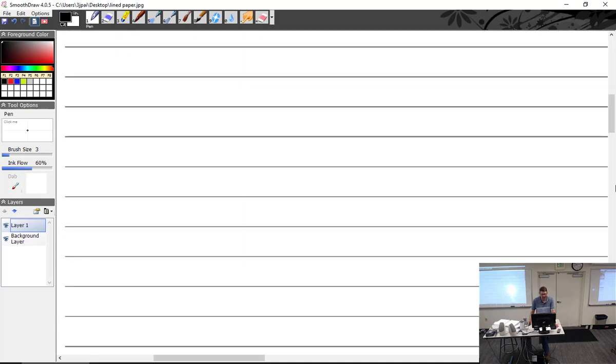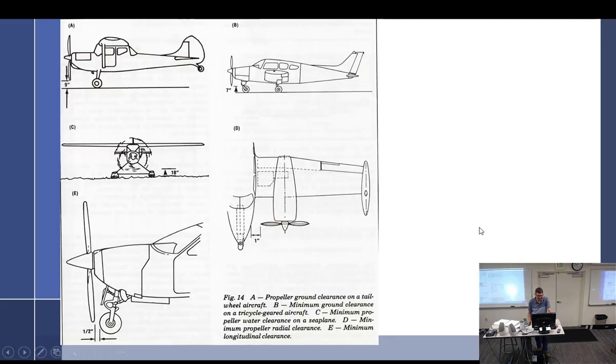Can you take a minute to explain positive clearance? I don't understand. No, there's no actual dimension. You just can't hit. Okay, just positive. Can't hit. Okay, negative clearance is when it hits. Got it. So yeah, 9 inches here, 7 inches there. Or if the strut were to fail or the tire deflated, positive clearance. 18 inches here, half an inch there.